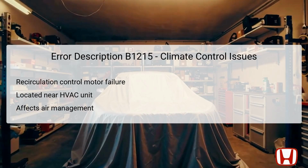Situated near the HVAC unit, this motor determines whether the vehicle uses recirculated air or pulls in outside air, contributing to overall air quality inside the cabin. When the DTC B1215 is triggered, it indicates that there is either an open circuit or a short circuit within the motor's wiring, leading to a malfunction. This malfunction can affect temperature management, potentially causing discomfort for passengers during extreme weather conditions. Proper airflow depends on this motor functioning correctly, underscoring the importance of addressing the underlying issues indicated by this DTC.